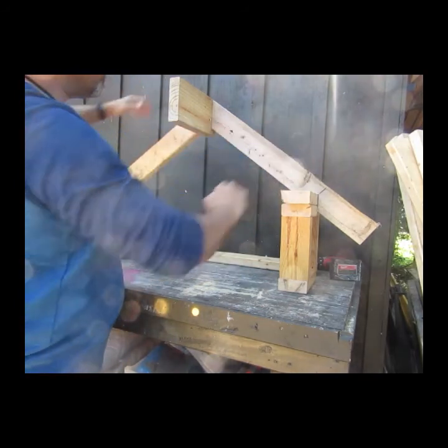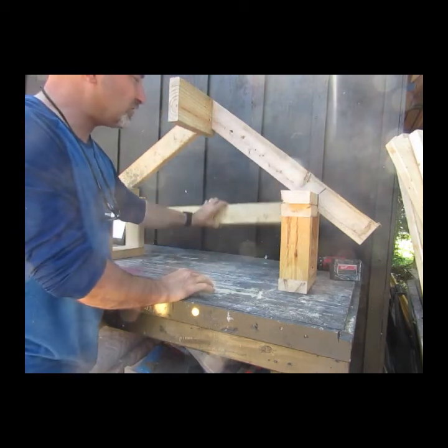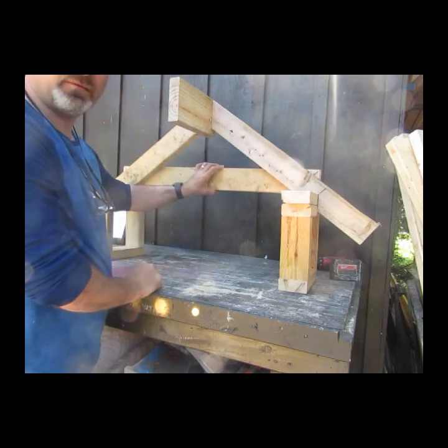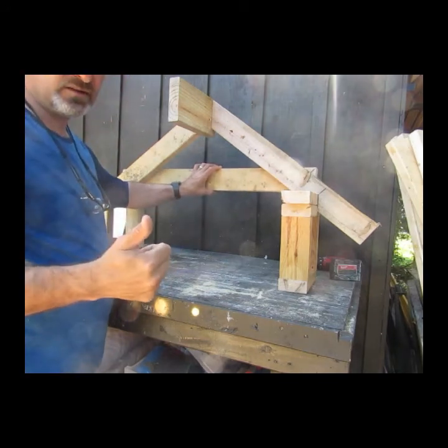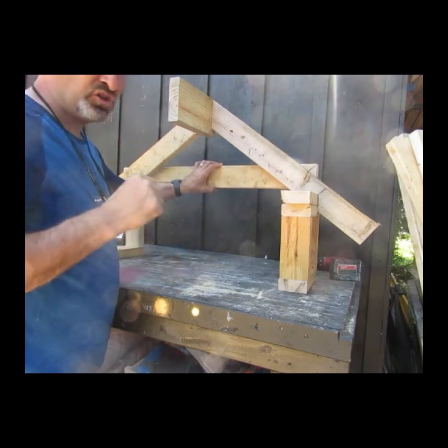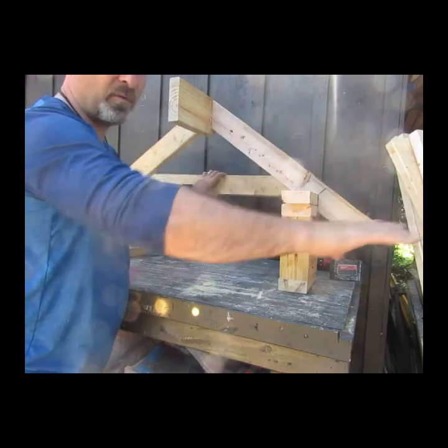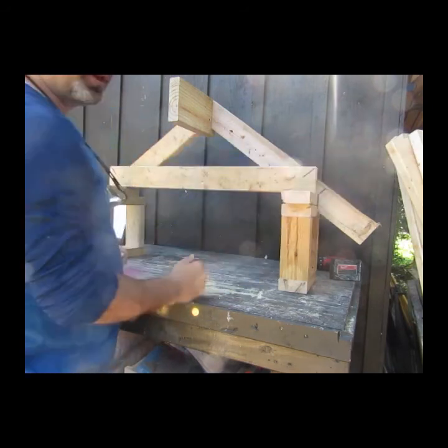The outward pressure, as I press down on the roof, the outward pressure of the walls is trying to stretch this rafter tie apart, and it's fastened to the left and right side at the bottom of each rafter. If the nails are of too small a size or the wrong type, well, the shear force will break those nails and it'll just come apart. But if you have the correct nails, it will stop it from pulling apart.